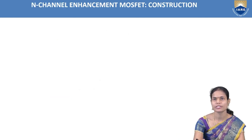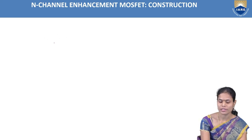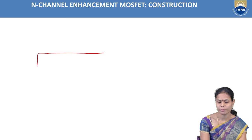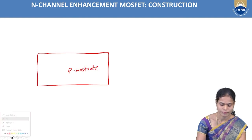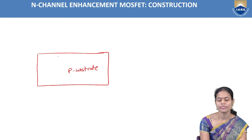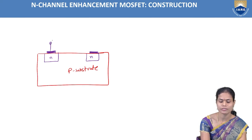And the next type of MOSFET is the enhancement MOSFET. In that I am considering the N-channel enhancement MOSFET. To construct the N-channel enhancement MOSFET, again I am considering the P substrate. On this P substrate I am diffusing two pieces of N-type material, and upon this I am providing the metal layer in order to make the contacts for the terminals.